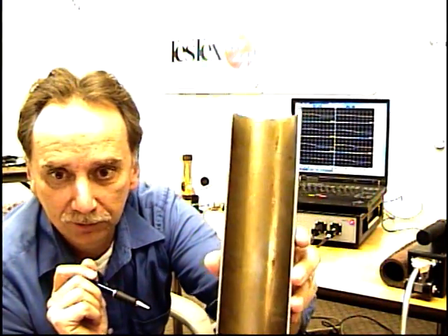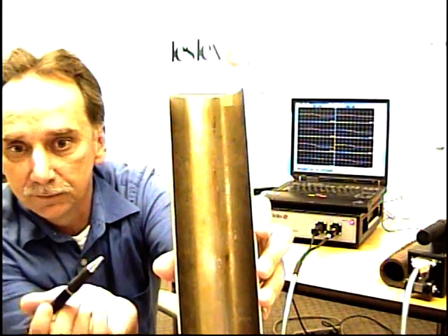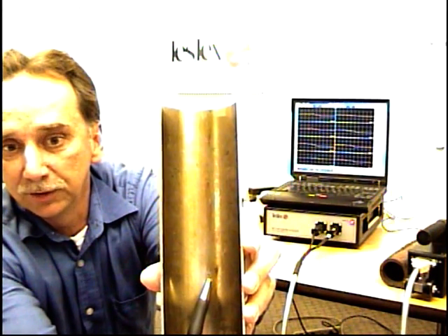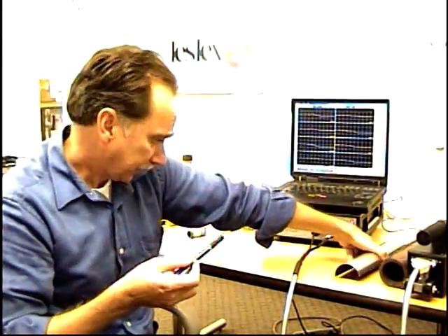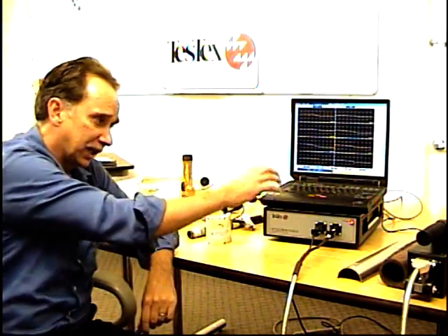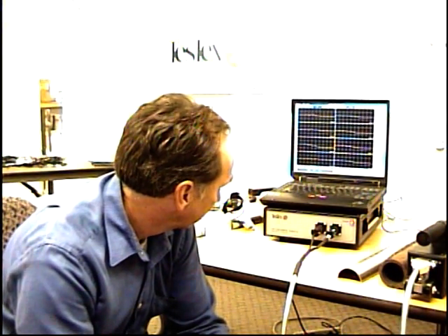Another thing I was telling you about is different types of material. This is for ferrous material, running at approximately 10 hertz. We can also do stainless steel. If you look in here, there's actually a small pit. It's kind of hard to see, but it's right there. By adjusting our frequency, we can scan over this tube and also pick up indications. All we have to do is adjust our frequency. This is probably about 1500 hertz. Same orientation, scanning along the length of the tubes. That's basically it for the LFET. It's short and quick, but it's one of our easier systems. And that's it.